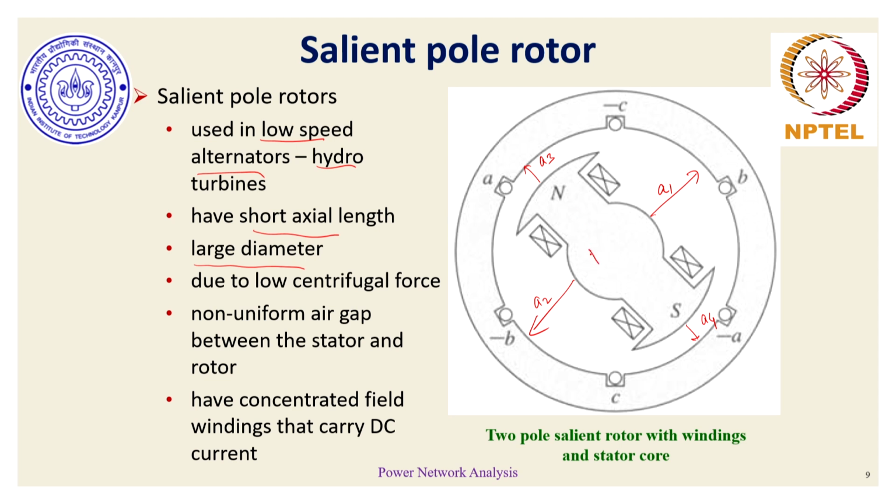So basically, this is the rotor here, and similarly, it is the case for stator here. In the stator, there are certain sets of windings carrying current into the plane, whereas the other windings are carrying current out of the plane. So the rotor winding here carries DC current. For this particular north and south pole, if we have to figure out what currents these windings are carrying, let's say this is rotor winding 1, rotor winding 2, then it's very easy that for a north to exist here, the current should be out of the plane here as per the right hand rule.